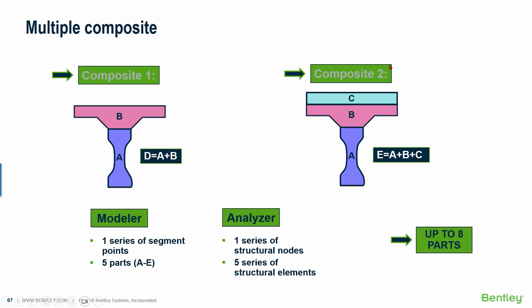So that means that we can activate different parts of the bridge during the construction, but we can also activate different parts of the cross-section itself with different materials, which is very interesting in that kind of cross-section, which is concrete and concrete, is that we have usually a pre-stress beam here that will support the traction, and we pour concrete once this is built. So that means that our deck will be mainly compressed.